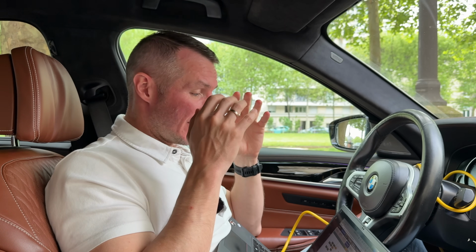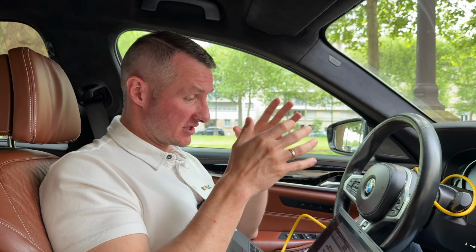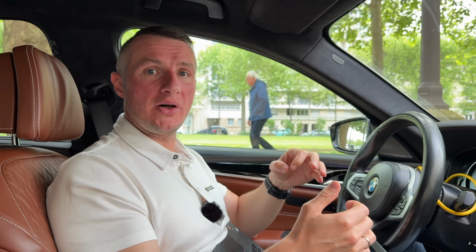Just for comparison, reading out that vehicle took me like 2 minutes. If I'm reading out the same BMW with the same computer but with the online ISTA, it will take half an hour, because ISTA needs to communicate with the BMW server and send information there. It is super slow, and standalone versions are way more stable. With the official online ISTA, it crashes. For example, you'll be reading out the car for 20 minutes, it crashes, and you have to start all over again. That's why diagnostics at dealership level sometimes take hours just to read out the vehicle, without even going into the details of what's actually wrong with the car.